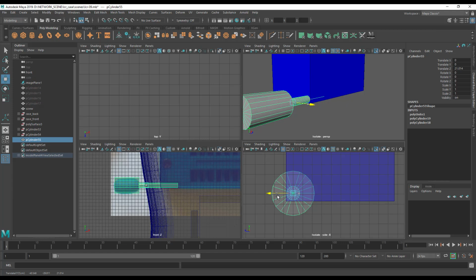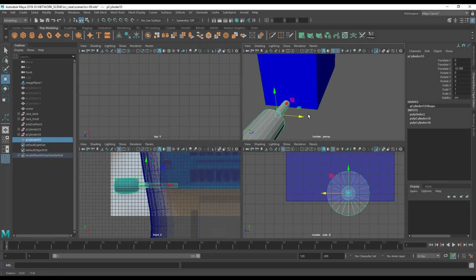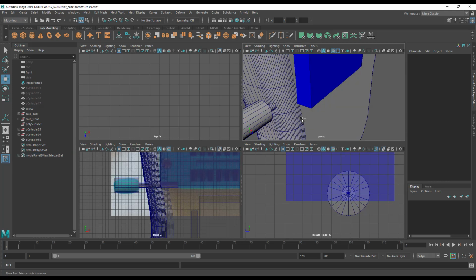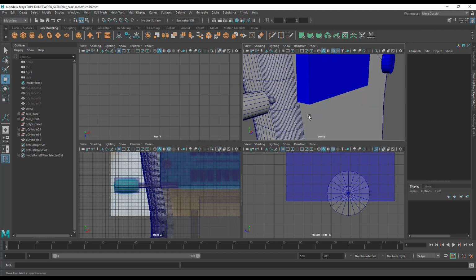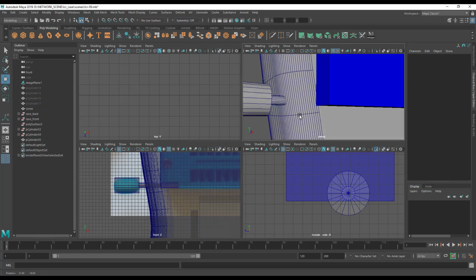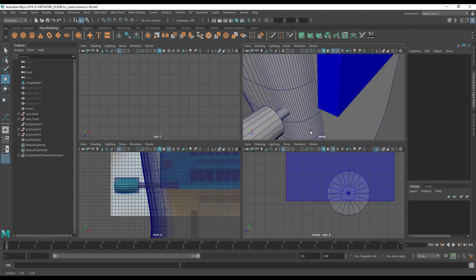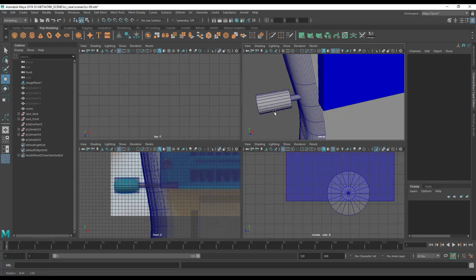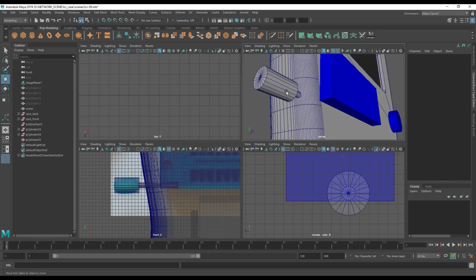So if we go, this being almost 1mm, 2mm, 3mm, 4mm, 5mm, 6mm, and then a little bit extra just to be on the safe side, and then we bring everything back, you can see that our bar here is most definitely intersecting the side of our case. So if we'd have printed as such, we wouldn't be able to fit the bar in.